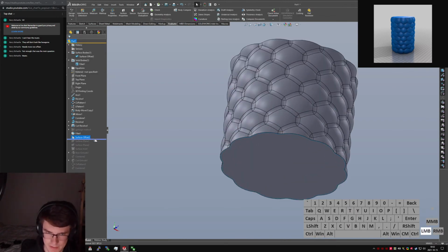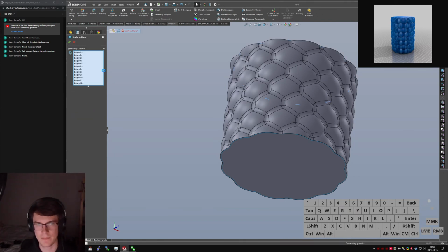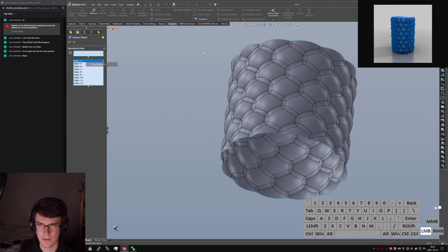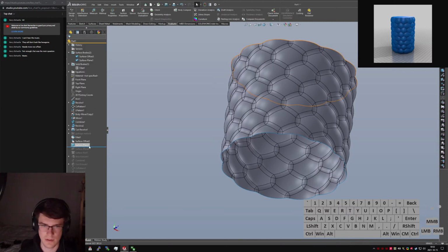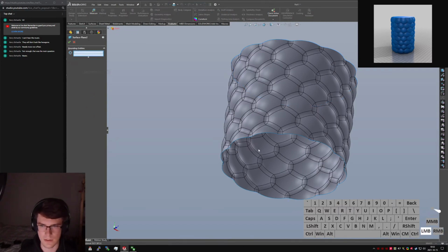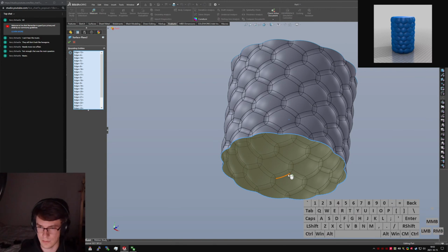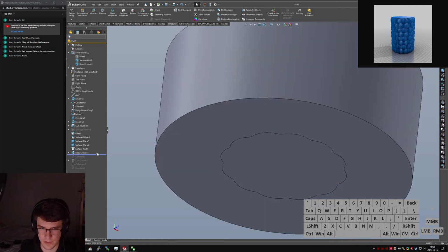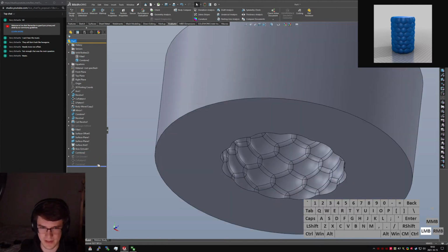Okay, well that gives us the new face. Planar surface is going to throw a fit. So we have to go hide the solid body. Regenerate these, which is fine. Expected having to do that. Select open loop. Generates just fine. Surface plane. Clear these ones. Select open tangency. Cute. Surface knit, that should work without a hitch. Boss extrude, work without a hitch. Combine 2, work without a hitch. I bet the rest of this is going to go just fine. I mean, it's going to take ages to rebuild because the number of surfaces has increased massively, but...